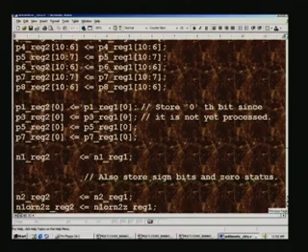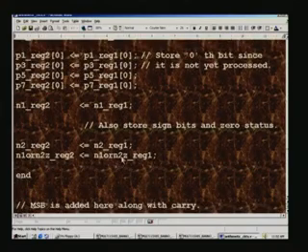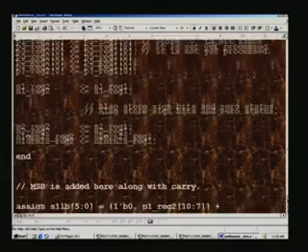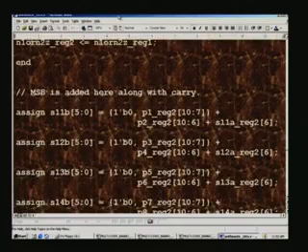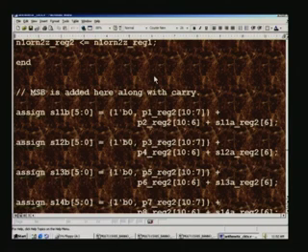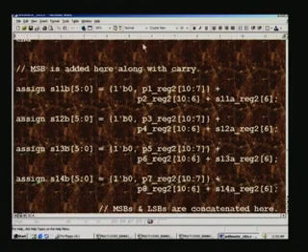Also store sign bits and 0 status, that is what is here, right, N1 sign bit, N2 sign bit, and whether N1 or N2 is 0 or the result is 0, that also is propagated. There is little scope for you to even optimize; you have a look into that and see where you can marginally optimize. I have not taken much trouble in optimizing, probably left it to the synthesis tool, but you can do it and find out whether your manual optimization saves any chip area. It will be very marginal, nominal, that is the reason why I did not dwell into depths.